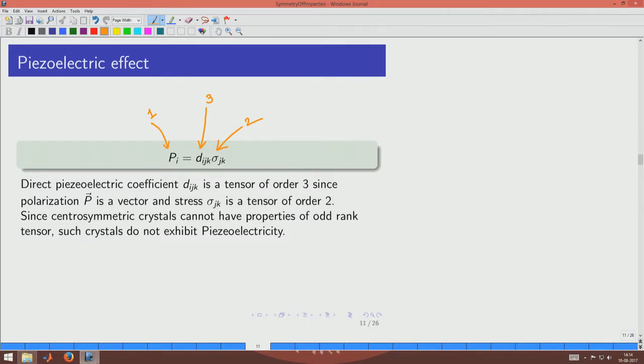And we can see that now we are getting a property that is actually odd ranked. There is a theorem which shows that if you want a material to possess a property of odd rank, then only centrosymmetric crystals will not be able to show it, non-centrosymmetric crystals can show it. This is something that we can discuss a little later on, but at this moment we mention that the nature of the tensor already is helping us, because certain symmetries of crystals cannot have certain properties, and that is very valuable, because this is a conclusion coming from the order of tensor, and that is coming from the mathematics rather than from experimental measurements.